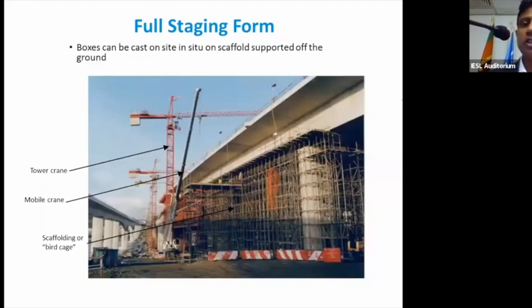Then the other option is the full stage. Rather than worry about this stitching together, you do a simple thing. You do a formwork, and you cast the box itself on top of it, and do the post tension. Here, the analysis is going to be changed because you'll be able to get the longer cables throughout. The analysis will be simpler than the other one because you don't have to worry about the changes of the deflection when you go to segmental construction, right? So that's one area.